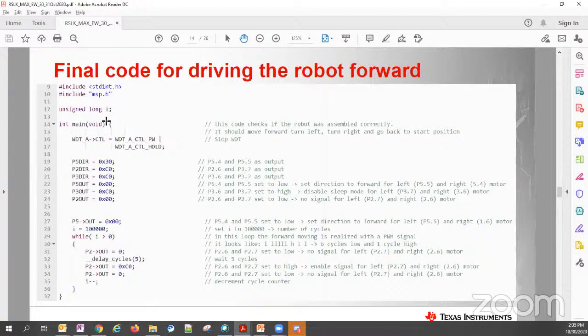So going back, let's recapitulate. Forget the watchdog timer, it doesn't matter, it's not important. What is important is to revisit what I've explained. The initialization phase ensures that all pins are programmed to become outputs and set up the right way, and makes sure the motor is off.